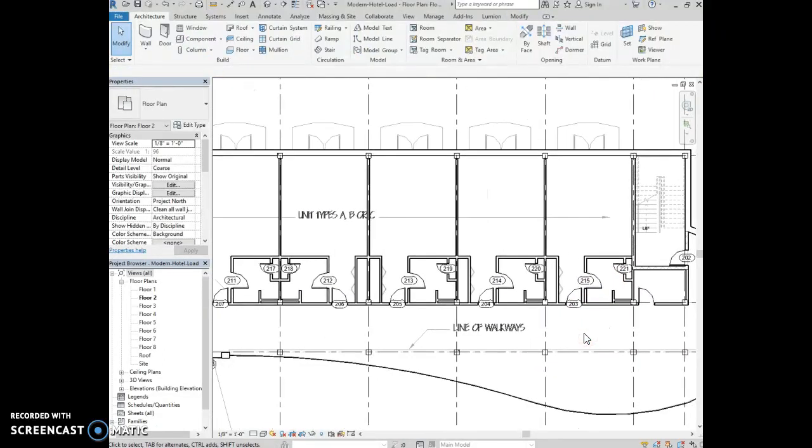And then you're going to continue this exercise by using different door styles. You're going to look for the bifold door, which is this door right here, and double glass. So double glass is the door up here. And you are going to add the bifold doors and the double glass doors to your drawing. Now you're going to have to determine the size of these doors when you place them in your drawing. So you may bring in too big or too small of a size, and it's going to be up to you to do some troubleshooting to figure that out.